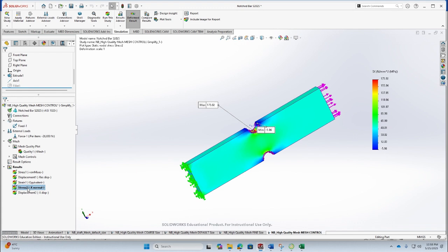So in reality, your full definition of the stresses cannot be completed unless you have x, y and z components as well as the shear components. That will then complete the definition. Although for these kinds of simple hand calculations we'll rarely need all of the components, in other cases where the stress state is multi-axial, you may have to look into all the components.